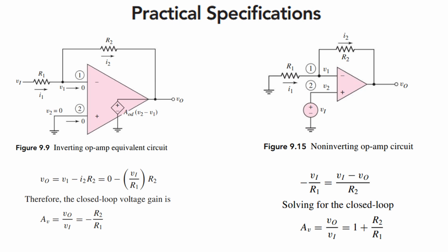So that will be equal to simply the V out minus 0 divided by R. Similarly, the current between the minus terminal and the V1 will be 0 minus V1 divided by R1. So equate this and get the output voltage, that will be equal to simply V1 into minus of R2 by R1. Similarly, we can also solve the non-inverting terminal, and here if we solve, then we'll get the gain, that will be equal to 1 plus R2 by R1.